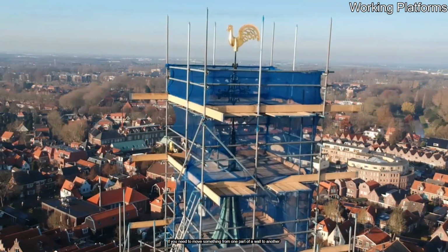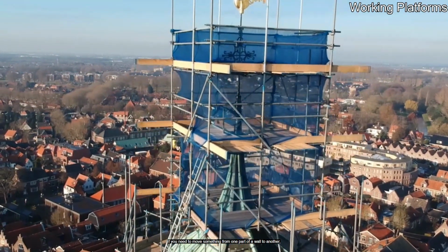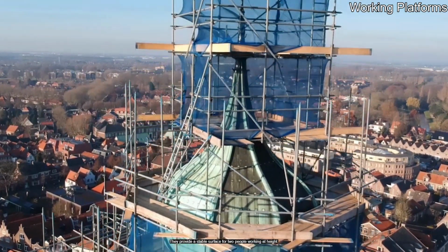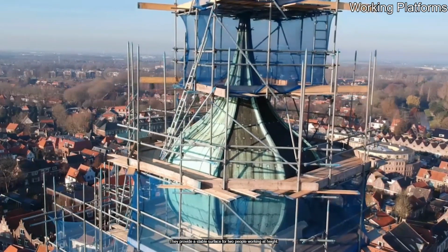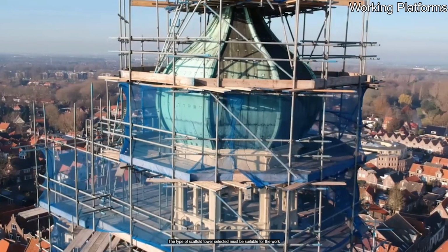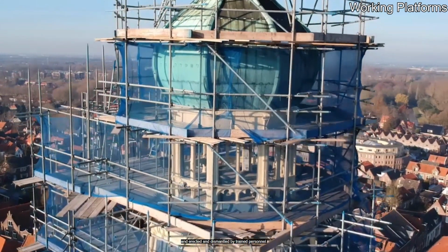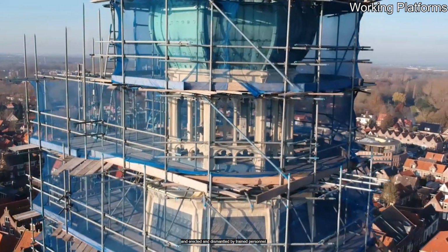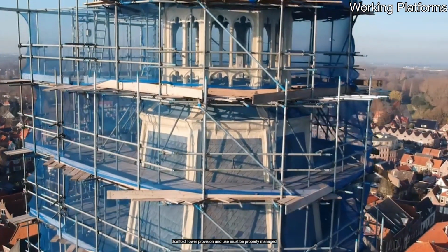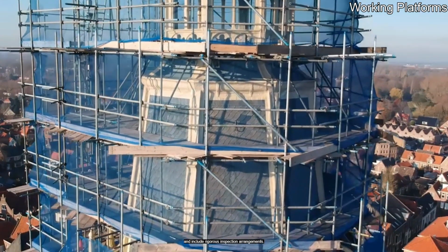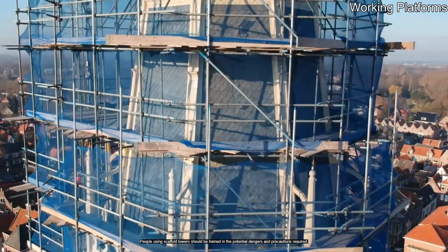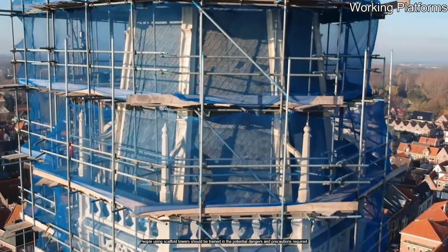If you need to move something from one part of a wall to another, a scaffold tower can give you the flexibility you need. They provide a stable surface for two people working at height. The type of scaffold tower selected must be suitable for the work and erected and dismantled by trained personnel. Scaffold tower provision and use must be properly managed and include rigorous inspection arrangements. People using scaffold towers should be trained in the potential dangers and precautions required.